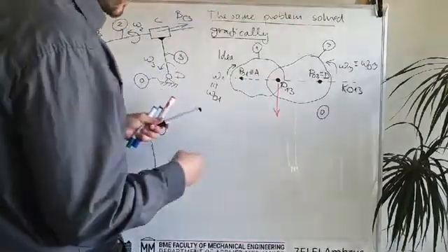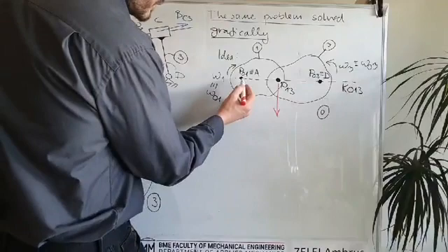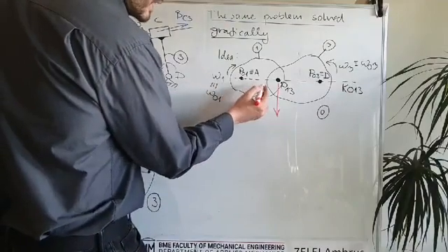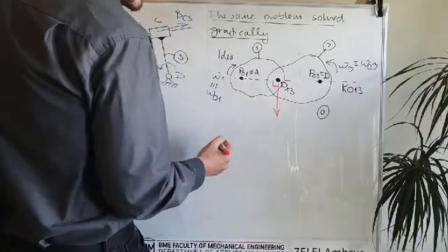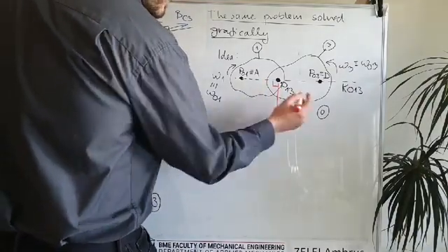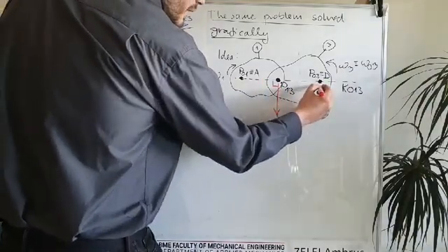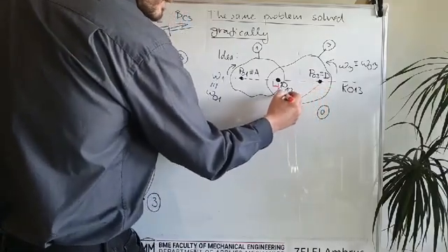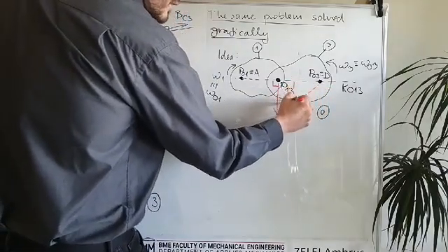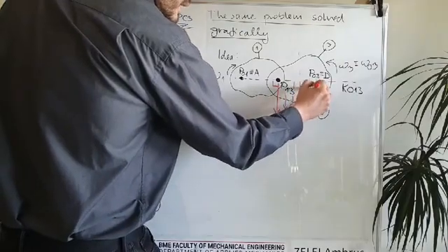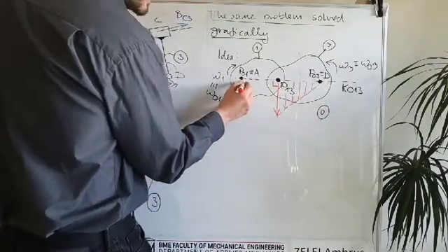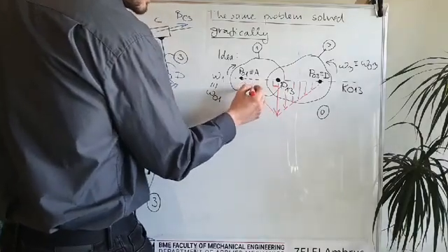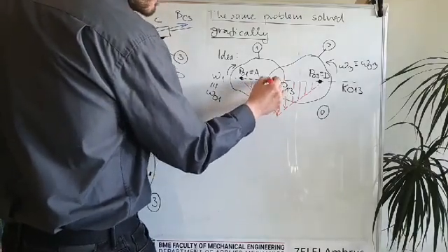From our earlier mechanical studies we also know that if it is fixed here, then this should be perpendicular here, and we also know that the velocity is 0 here, so finally we can draw this line which tells us the velocity of each point of rigid body number 3, and we can say the same for rigid body number 1.